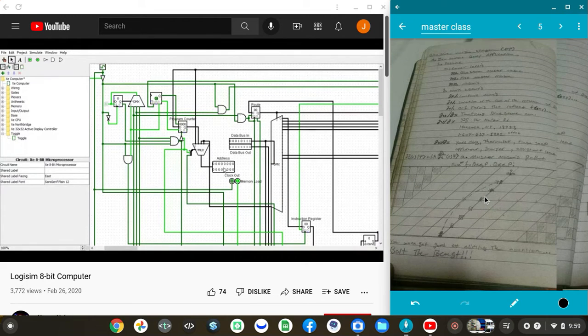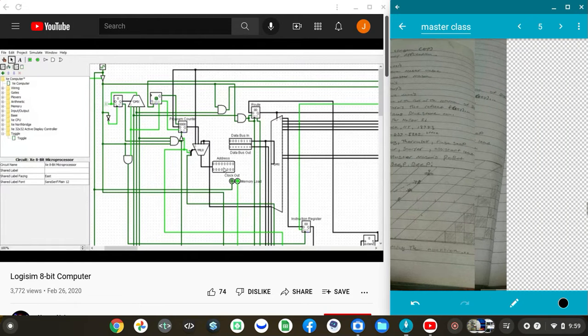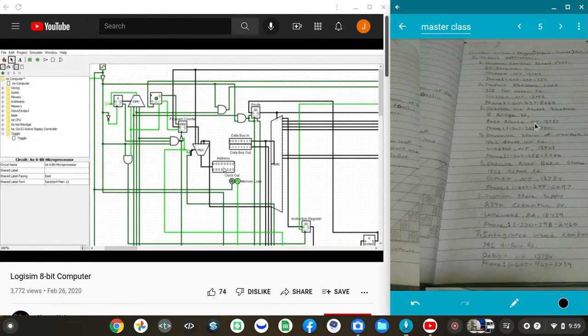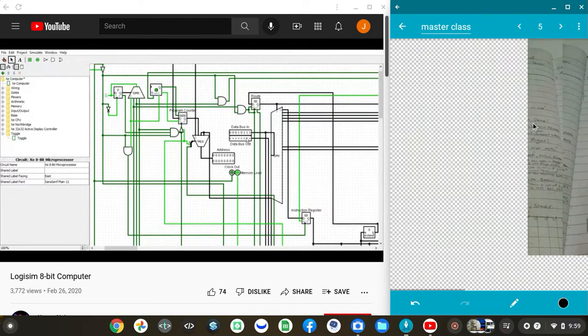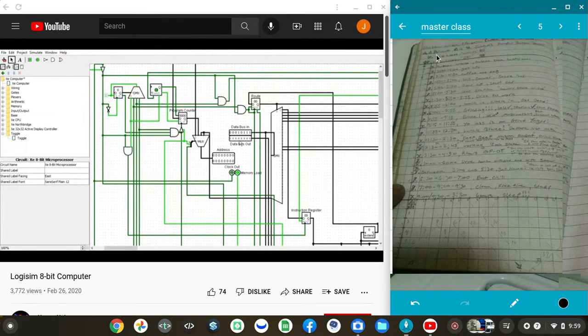Because it's at address 0, which means it's looking at the very first byte in the ROM. And I know what I put in the ROM. The first thing that's in there is an instruction. And the first thing that instruction does is copy a block of other instructions into the RAM. And then it jumps to the RAM and starts executing from there. So, yeah, and this data bus out is whatever data is coming out of the CPU.